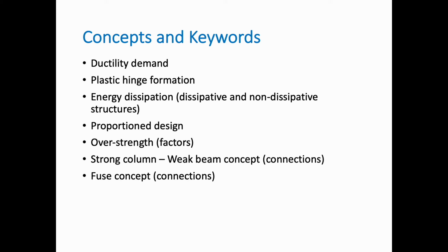With that, the fuse concept has been one of these that we use quite a lot nowadays. The fuse concept in principle is exactly what we said before, strong column, weak beam, but in steel structures in particular, we have taken it to another level where we are talking about fuses, which, like fuses, can be removed and replaced.